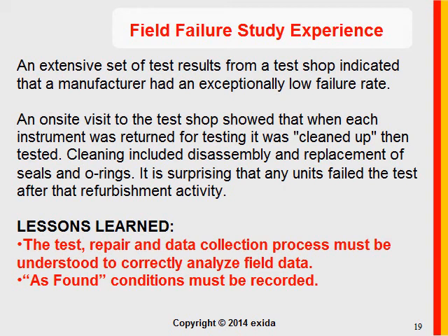So take the opposite approach. If you clean it up, if you fix the unit before you start testing, it's really surprising that any units failed after all this refurbishment activity. So in this case, the exceptionally low failure rate wasn't a real field failure rate. It was a failure rate after the refurbishment. And arguably this would support the claim that a maintenance capability, or taking into consideration the performance of your maintenance crew, is something that we should take into consideration, because apparently in this case not all failures were fixed with this cleaning up activity.